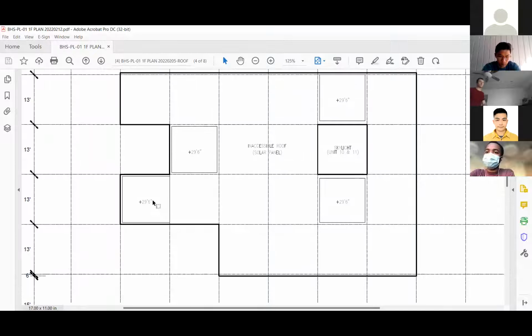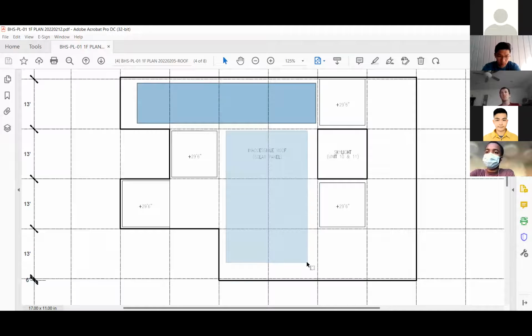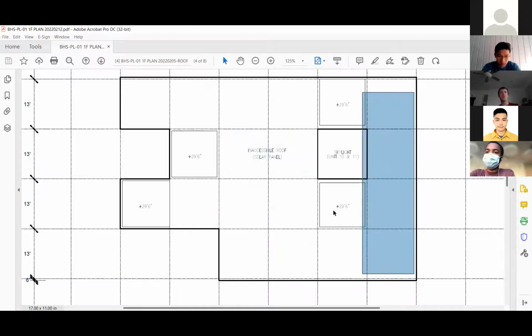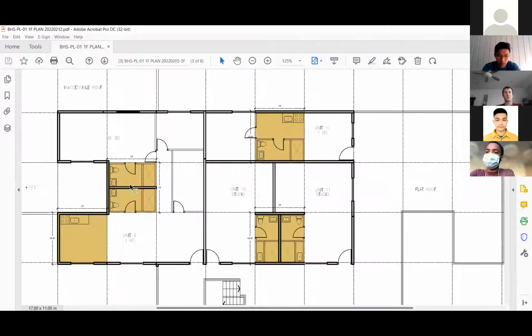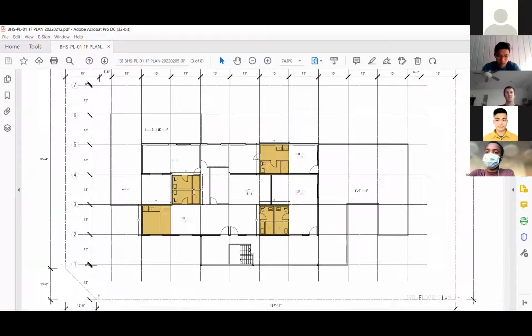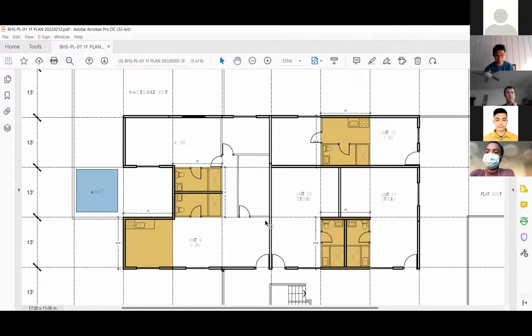For example, for the top roof floor, these 4 areas would be where the levels are slightly lower than the general roof space here. So these 4 areas could be the drainage zones, to put the drainage points, which can also connect with the areas that already have utilities, to connect vertically all the way down, which also happens here.